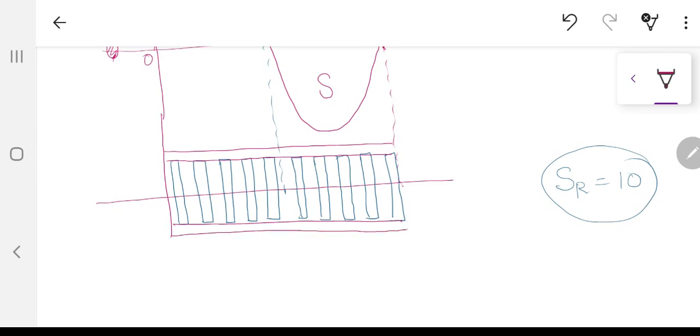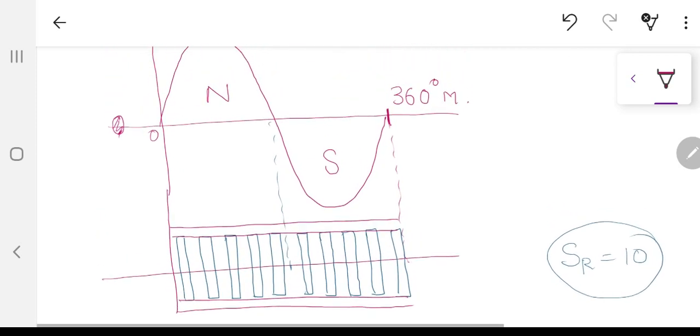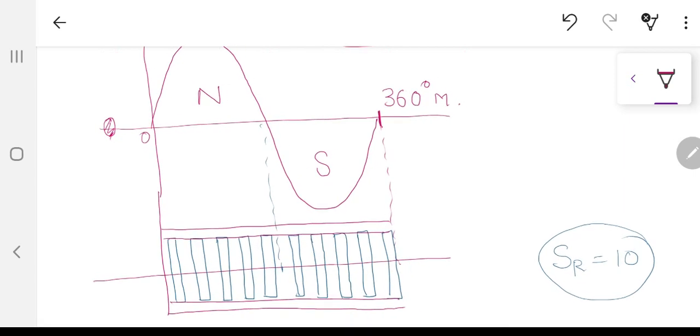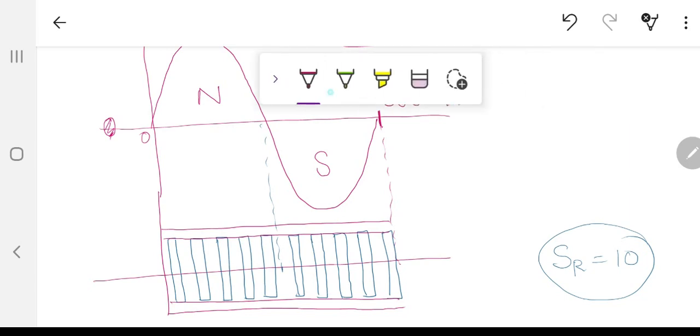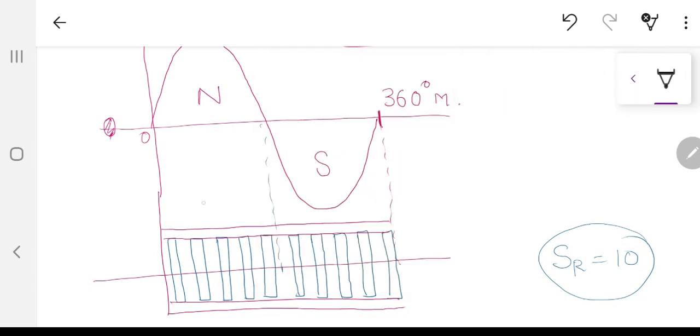The whole rotor, which is actually circular in shape, is now opened on a piece of paper with all the bars shown in front of you, and dependent upon the MMF waveform produced from the north and the south pole, you are going to have an EMF induced inside the bars based on the value of that flux, which is changing sinusoidally through space. So corresponding to the first bar, you are going to have a very small value, so I can call it a very small arrow. The next one is going to be a little larger.